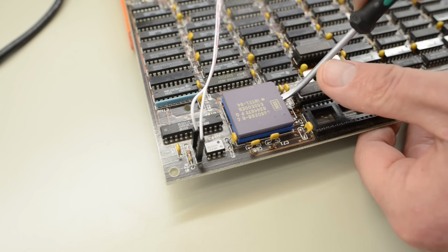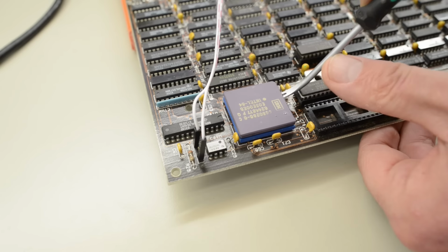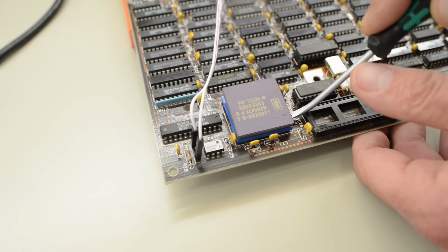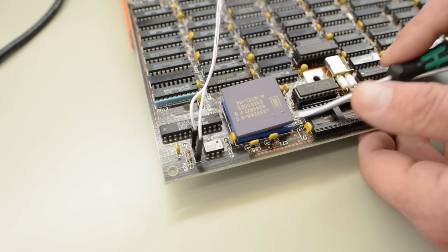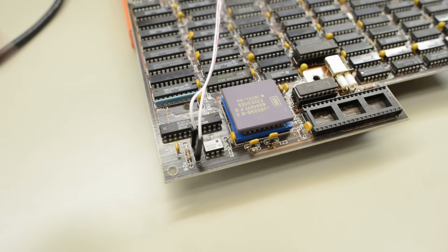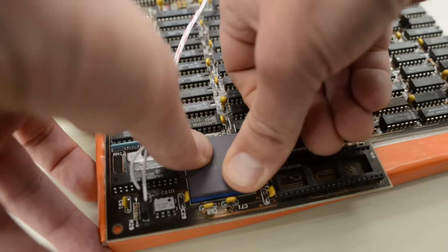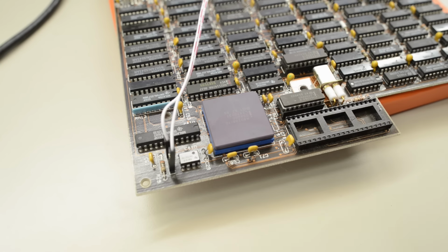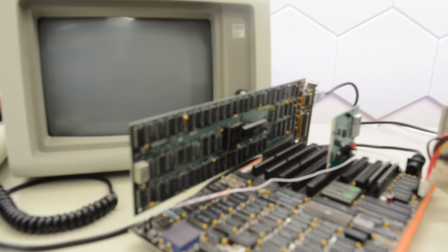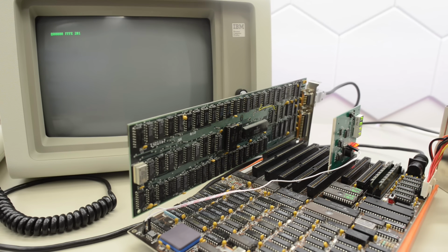Next thing to try is highly unlikely, but since we are going to upgrade the CPU, we might as well do it now and eliminate one more possible fault. Even if it's unlikely. The CPU is much faster than the original 286. Okay, let's do tests. And as expected, it didn't make a difference. But now we have one thing less that could be faulty.